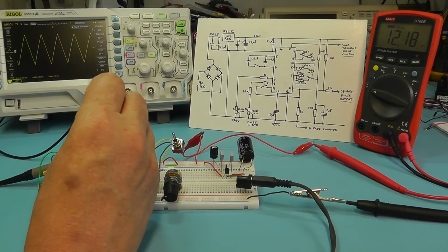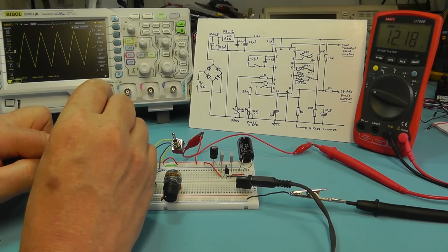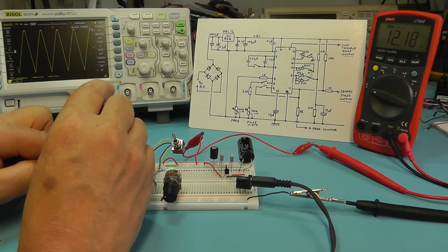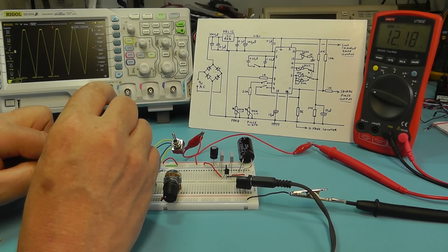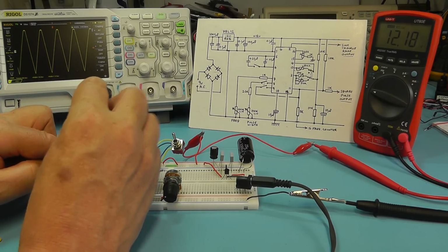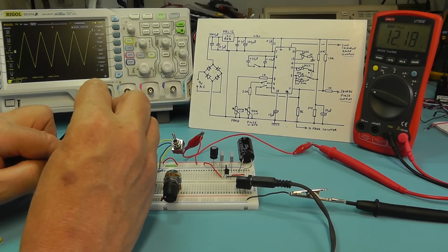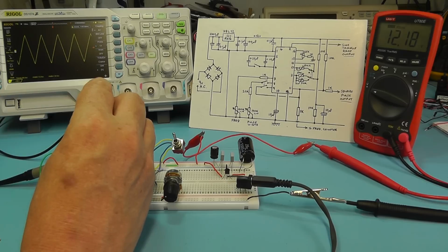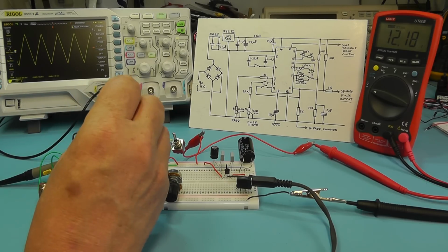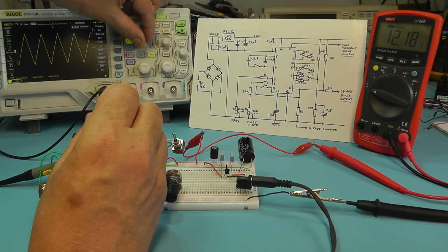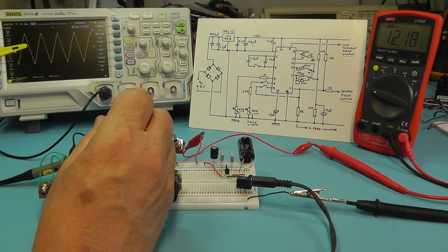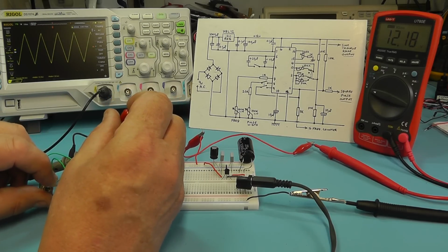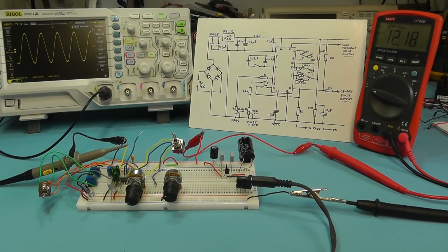But if you go too high on that, I'll just demonstrate that. You'll see it's clipping now at the top. See how it's starting to clip. So let's take it back down to 5 volts peak to peak. So there we are, we've 1, 2, 3, 4, a little bit there. So that's reading now about 5 volts peak to peak. Switch back to the sine wave, and again we've got 5 volts peak to peak.